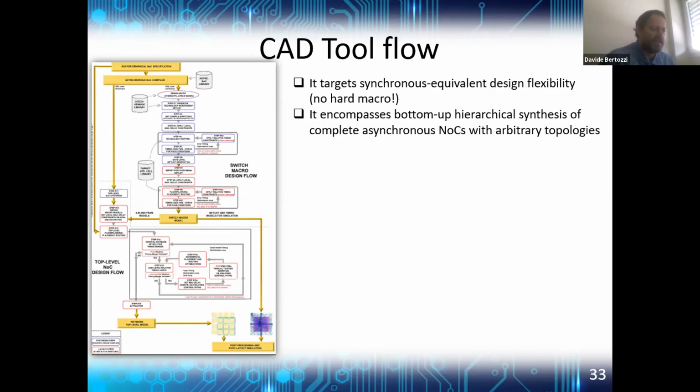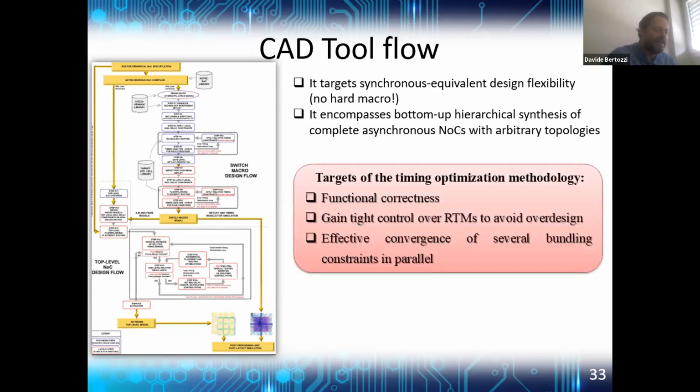Without loss of generality, this tool flow has currently been tested with mainstream CAD tools such as Synopsys Design Compiler for logic synthesis and Synopsys IC Compiler for place and route. And the flow revolves around a detailed timing optimization methodology. That's the cornerstone of this CAD tool flow, the timing optimization methodology. It has been designed with the following goals in mind.